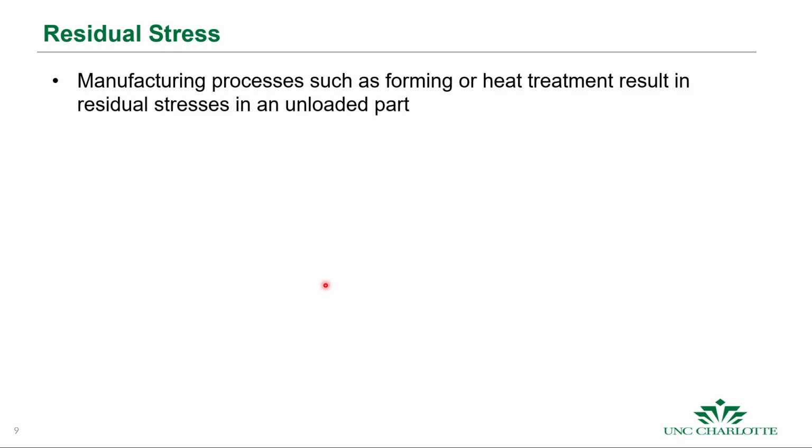Sometimes these are residual tensile stresses, sometimes they're residual compressive stresses, but they're extremely important for us because the residual stress in the surface can dramatically affect the fatigue life.